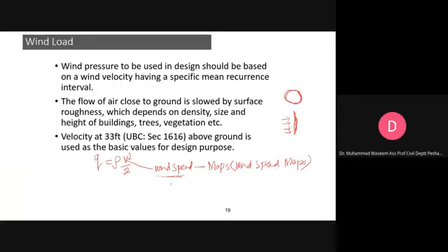correspond to a certain probability of occurrence during the lifetime of your structure. And the design maps or wind speed maps which are used in the IBC, or which are used in the loading code. What is the name of the loading code? ASCE 7. So it recommends usage of some maps. Obviously this code is for the USA. Now, this code suggests to use some wind velocity maps.